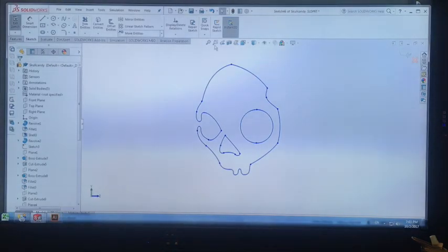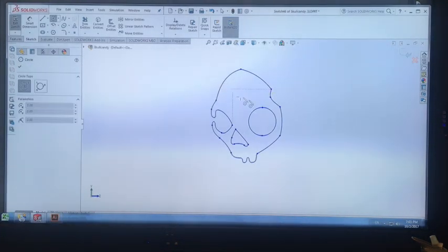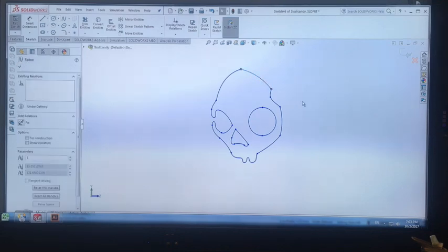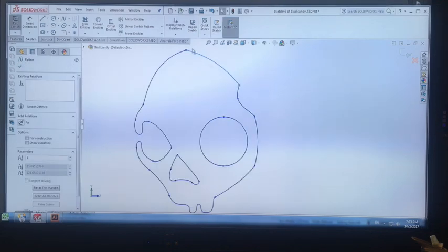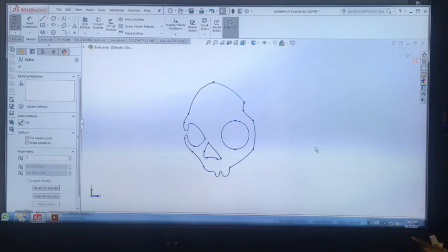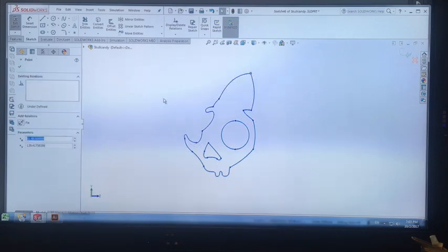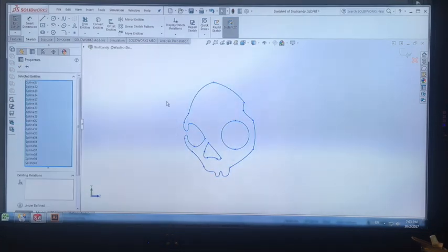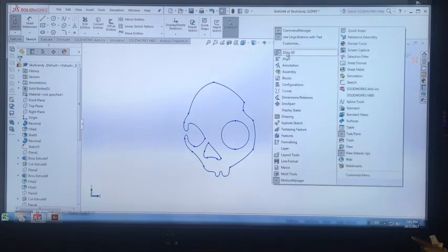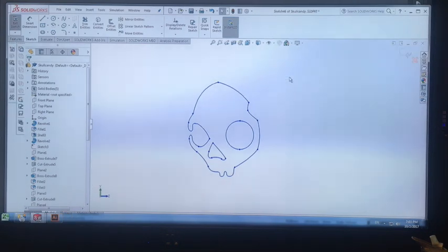Okay. So what you can see, those little ellipses, that part of that circle here, that's now changed to a spline. Most of these lines are actually splines in this object. So not really easy for editing, and again, not great for trying to move, as you can see what happened there. So when you have something like this that you bring in, you need to turn it into what's called a block. You can turn on blocks on your toolbar: right click, go blocks.